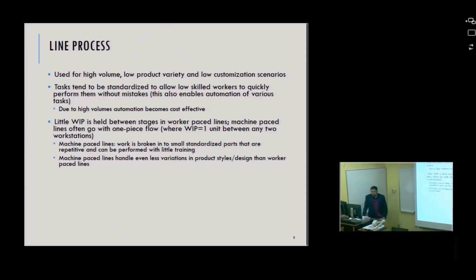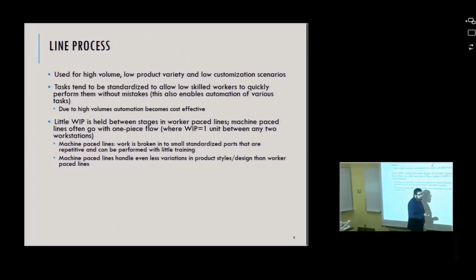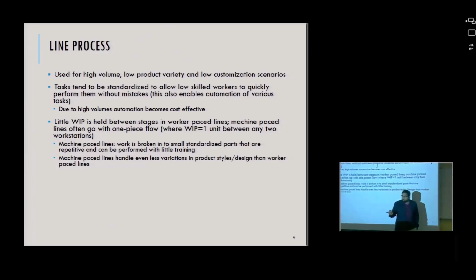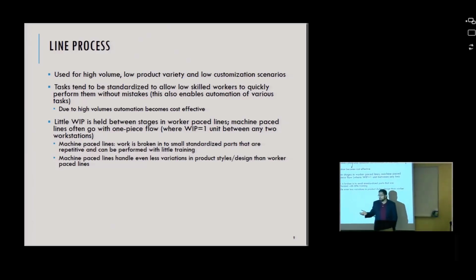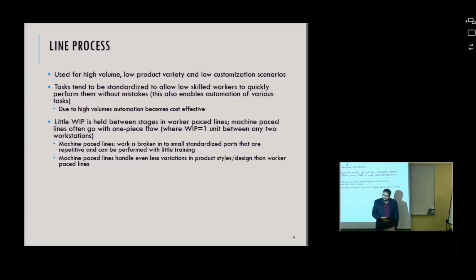Okay. Why would you go for worker paced versus machine paced, or when would you go? Well, when can you do machine paced? When would you do worker paced? Right, so machine paced has a much higher fixed cost to set up. You have to set up all the conveyor system. Plus, in the machine paced, workers have to work at the same pace. Now, if you're doing something very simple, like tightening some screws, installing something, that's fine. You can kind of see how long it takes and if it takes the same thing every day, right?